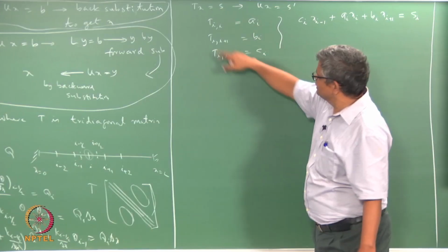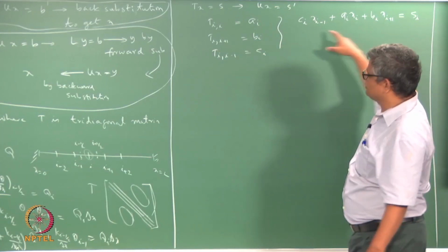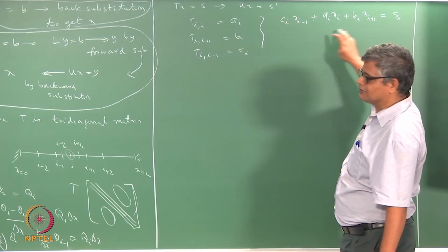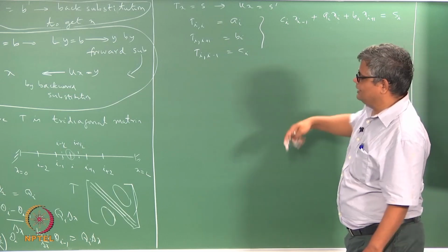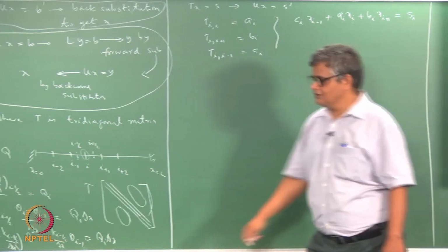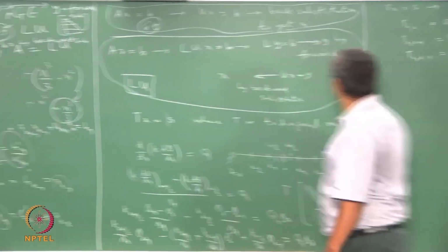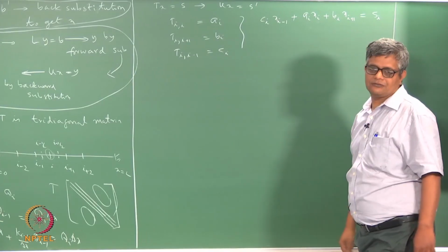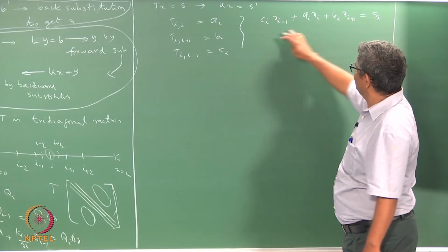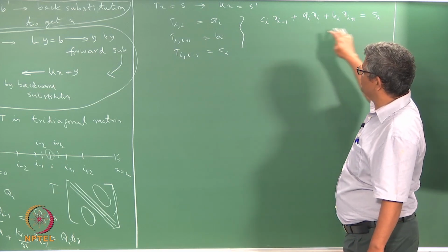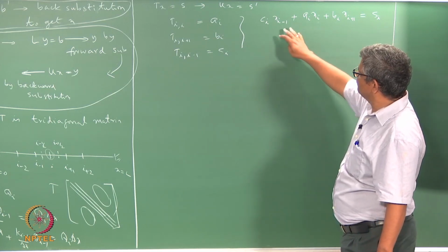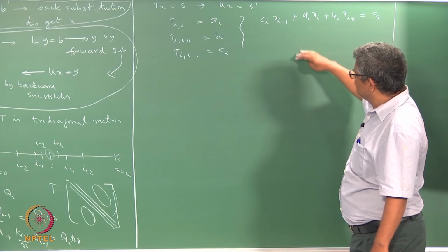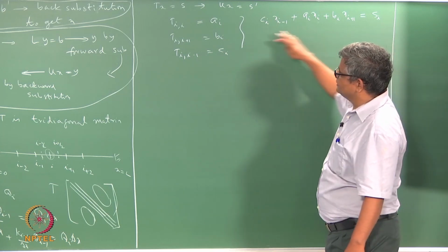And this formulation is such that each of these coefficients can change from equation to equation. You can have some special cases where all the C's are constant and all the A's are constant. For example, in the simplest case where K, the thermal conductivity, is constant, we normally have C equal to 1, A equal to minus 2 and B equal to 1. Okay. So, this represents a tridiagonal, a linear algebraic equation involving 3 adjacent neighbors, and when you go for all values of i you get this type of form.